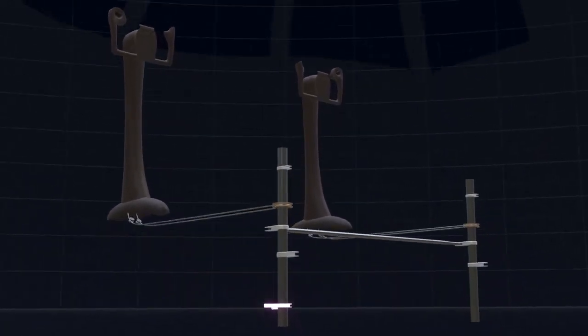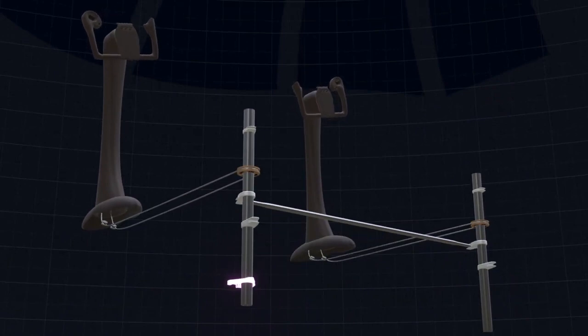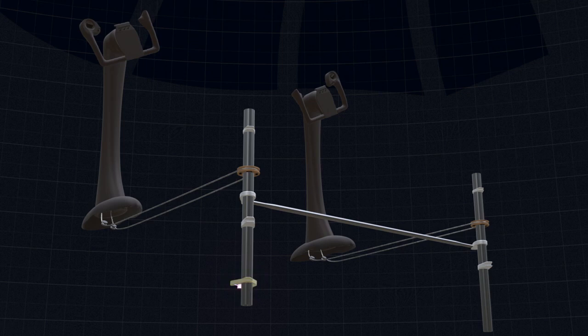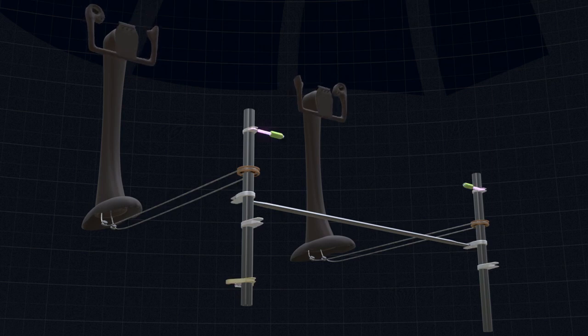Feel and centering mechanism provides the spring force to the control wheels. The further it is rotated, the harder it gets. And once the wheels are released, the spring returns them to the neutral position. Let's look at the aileron and flaperon deflection due to control wheel rotation.